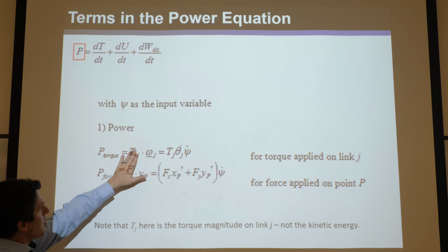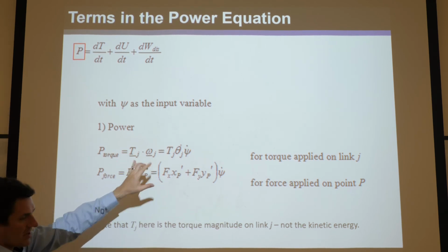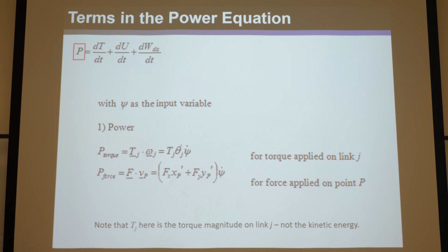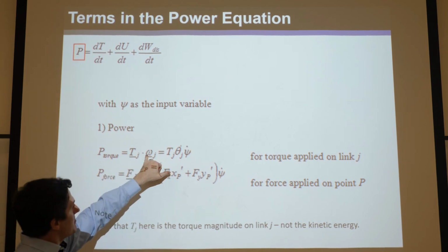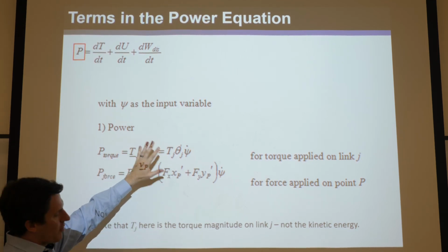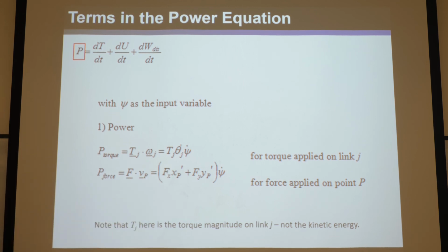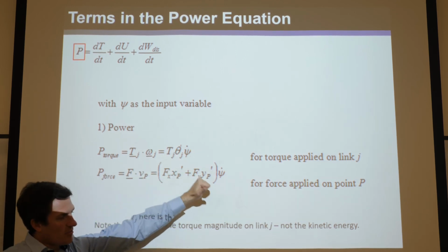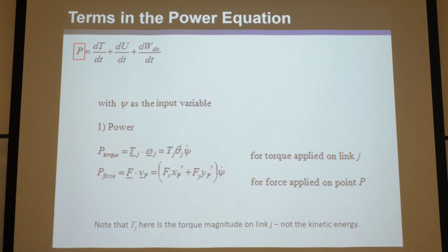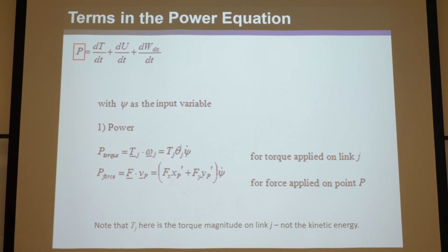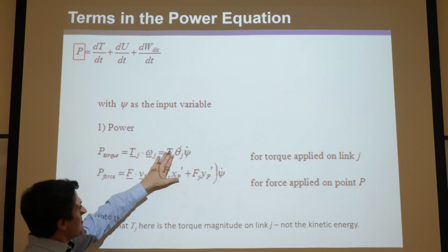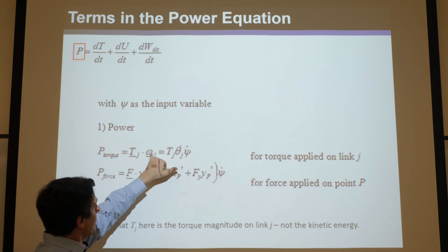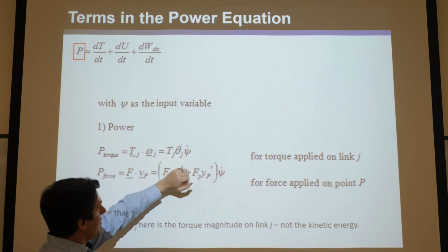And so here the power is torque times angular velocity. Okay, you know that's angular. That's power due to angular rotations. And you dot product, then you take the magnitude of this times the magnitude of this. And remember, for planar scenarios, you don't really need a dot product. You don't see any cosine here because they're both coming out of the page, and the angle between the two is 0, so the cosine of 0 is 1, right? So you take the magnitude of that times, just angular velocity magnitude, which, by the way, if you recall, is